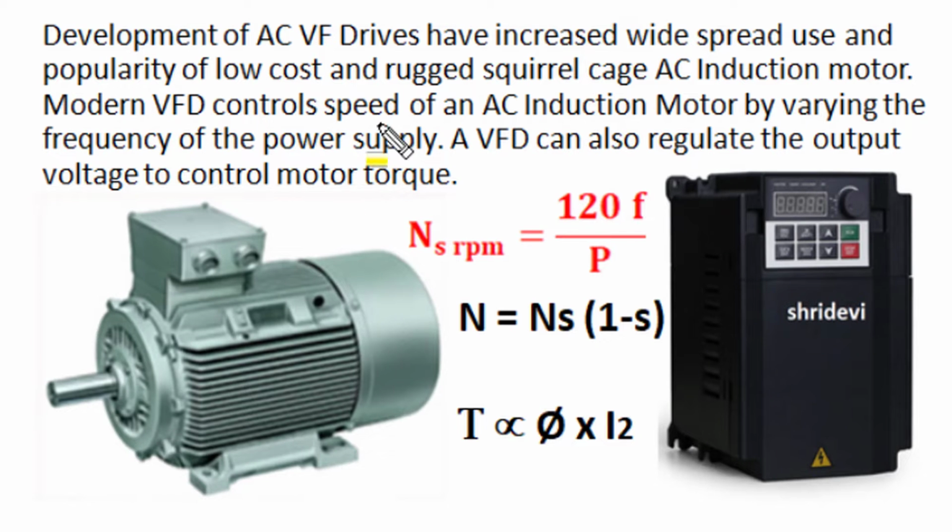Development in modern power electronic switching devices such as IGBTs, improved design and development of converter circuits, and development in the field of microcontrollers and feedback tools have increased the widespread use and popularity of these variable speed drives for variable speed operation of electric motors.